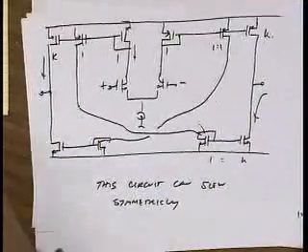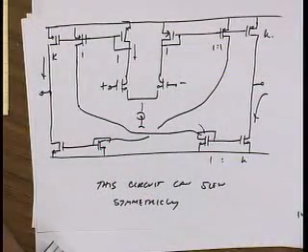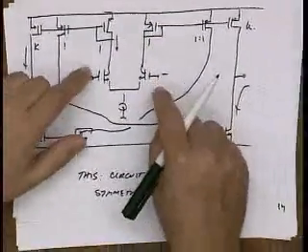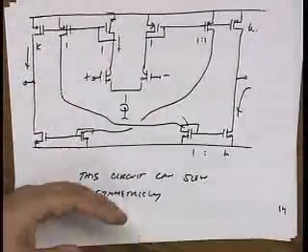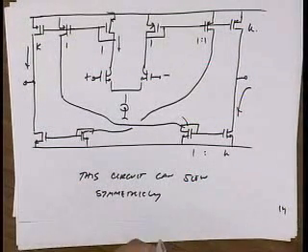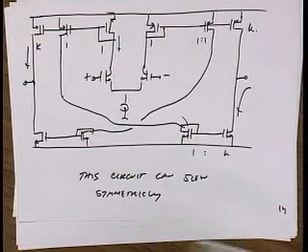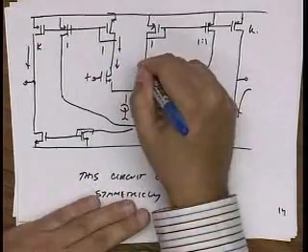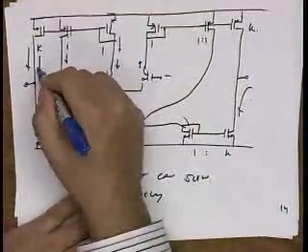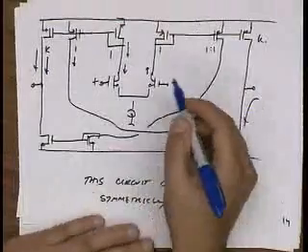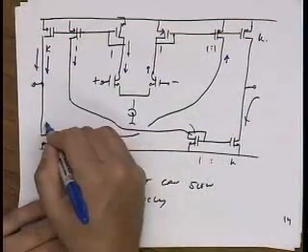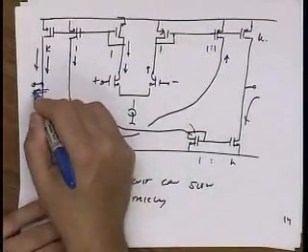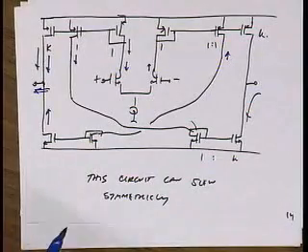Yes. What happens in the normal case when there's no slewing? Like you get double the current? Yeah, so if there's no slewing, it all still works out, right? So all these arrows I've drawn, use a different color pen. Under small signal conditions, right? This gets copied over here, and this current gets mirrored over here, and then gets mirrored over here, so I end up getting twice the current. That helps the gain as well.